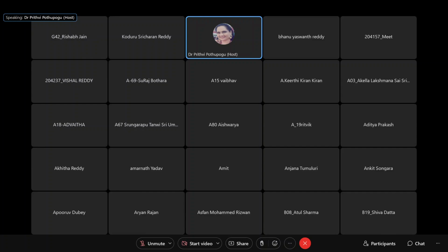The topics, okay. And I think the last topic where we have stopped is the built-in self-test, BIST. Yes, BIST we have seen. In that BIST, I think linear feedback shift register, that is the other name of pseudo-random pattern generator, was explained. And what were the different taps we have seen? What is the meaning of these taps?